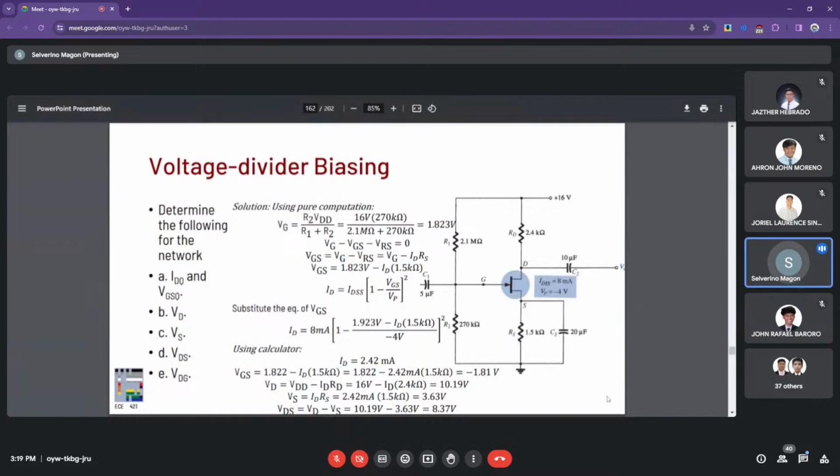the disco, no? In the DC, inductor is shorted, capacitor is open. The DC supply of 10 volts from the drain connector here is not being measured in the output actually. So we only have a DC reference here. This lifts the output at some 10 volts above zero, no? So that's what it means. But after this capacitor, this is zero already because in DC, this is essentially open.